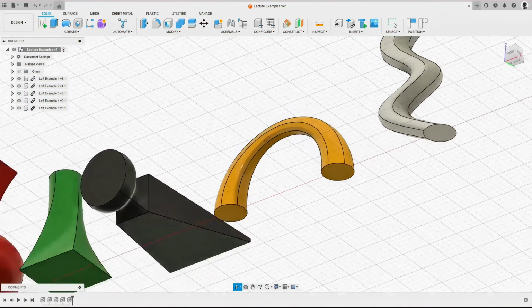Therefore, we're going to use the construction. We're going to offset a plane, and we're going to offset in this case from the XY plane. We're going to come up vertical, and that's going to be a dimension of 75 mil. Press enter. Let's put in another plane then. Let's offset from this one here. Let's go another 75 mil. And let's do one more as well from this one. Go up another 75 mil. So we've got our 3 added construction planes, and we've got the default XY down here.